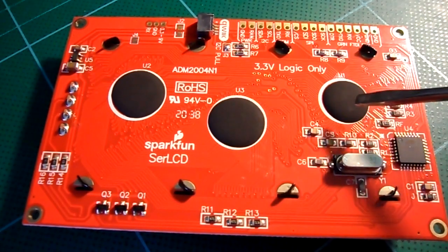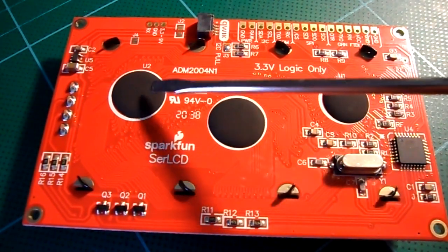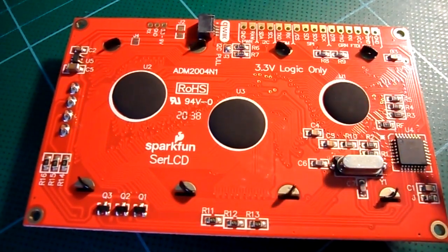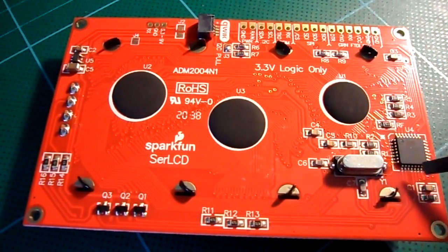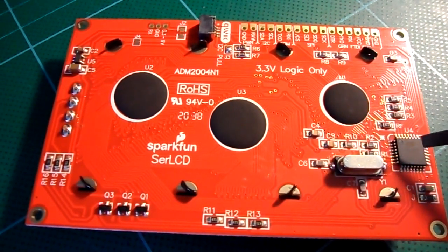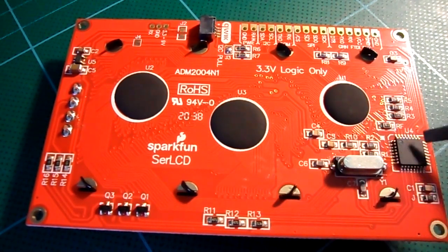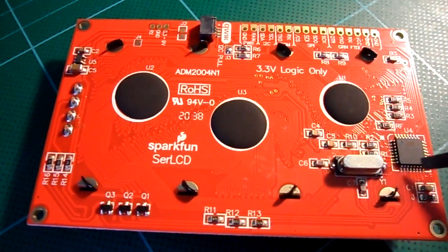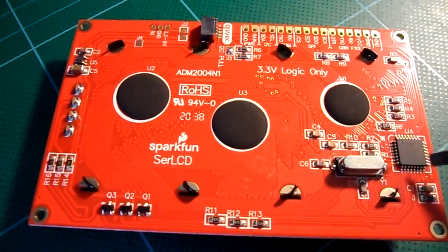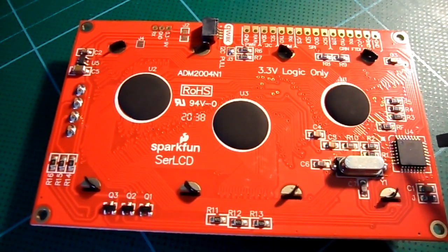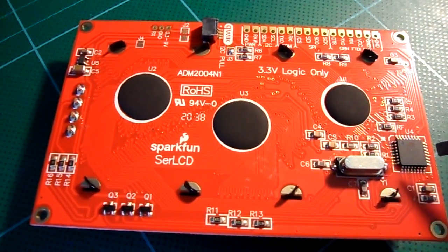The SparkFun LCD only returns one address because it uses the HD44780 LCD controller, but to communicate over the serial communication protocols, it uses an ATmega 328P, which provides serial, I2C, and SPI. So let's take a look and see what the Waveshare LCD1602 RGB module is using.